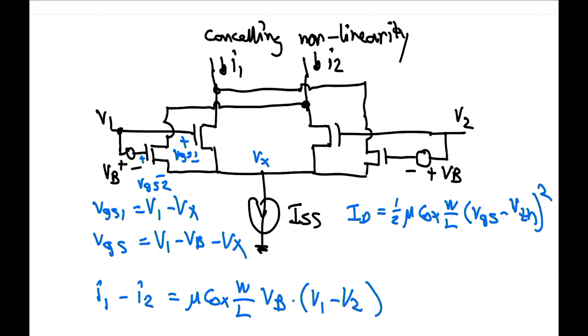Okay. I think that actually this circuit will consume a lot of power, especially using a source follower to implement it, because the effective voltage for the VGS will be pretty big. Will it consume a lot of power? A lot of current, right? You have a number of branches, yes. If you put source followers in for the bias voltage, then you have 3 branches of current.